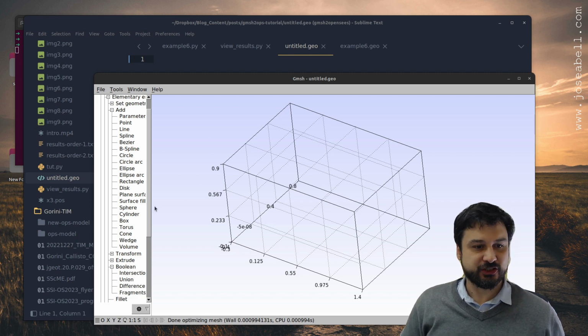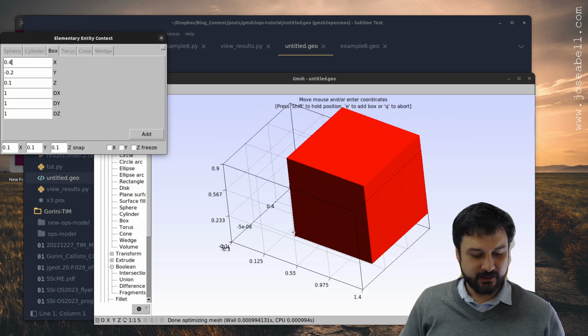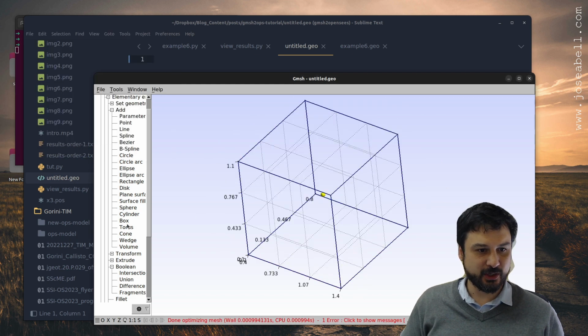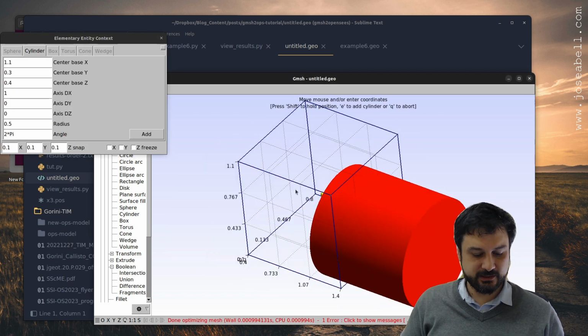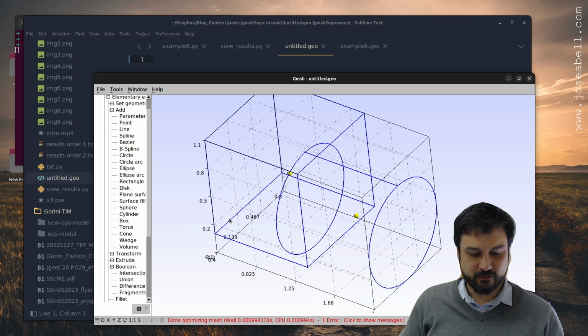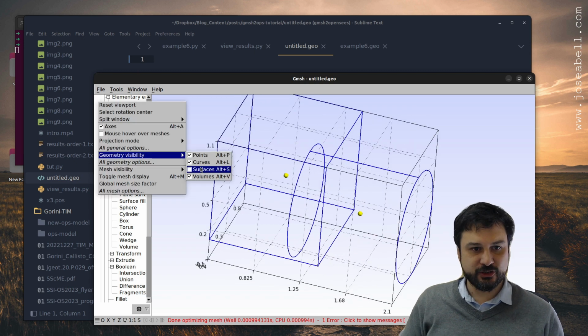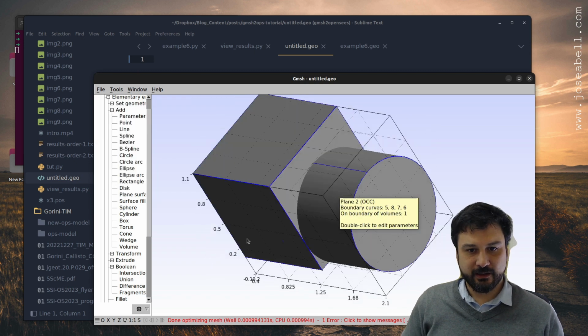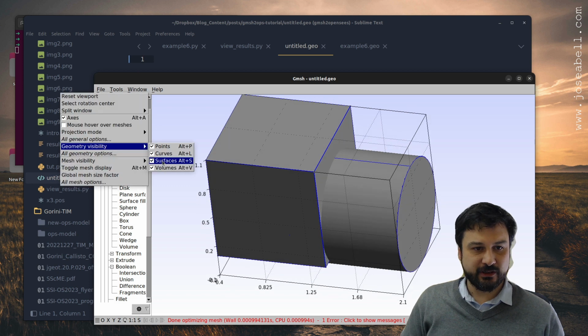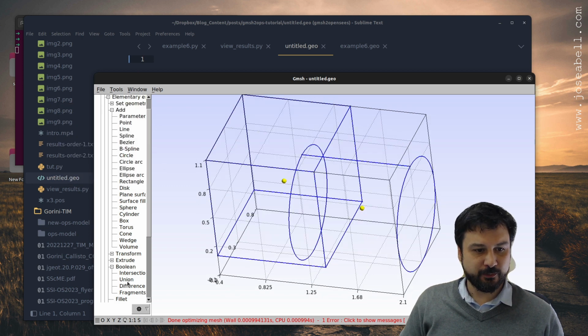Tetrahedrons are just awesome. Let me show you why. Let's add a little box here. That's a box. And let's add a cylinder to go right next to it, right there. And you can see these are two figures where they have not been joined yet. So let me merge them. I'll merge them with a Boolean union.